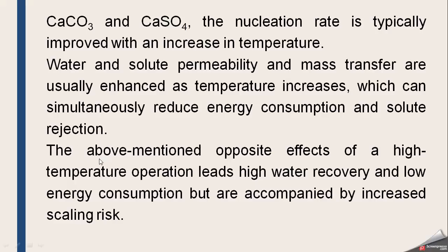However, the above mentioned effects of high temperature operation lead to high water recovery and low energy consumption, but this also leads to higher scaling risk, because when more water is passed through the RO membrane, the remaining water is left with a higher quantity of solutes, which already contain some scaling compounds, and so scaling on the membrane surface increases.